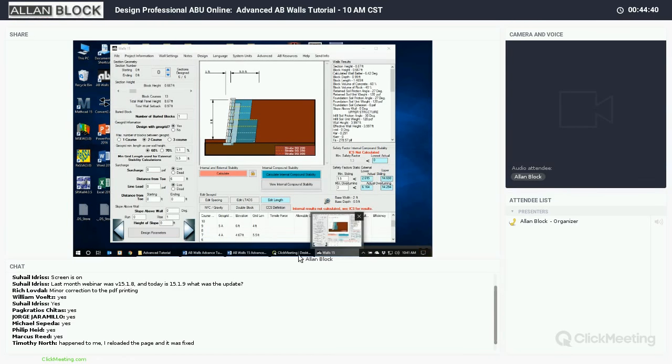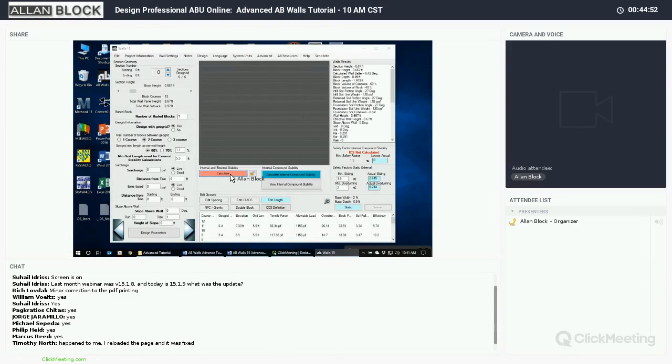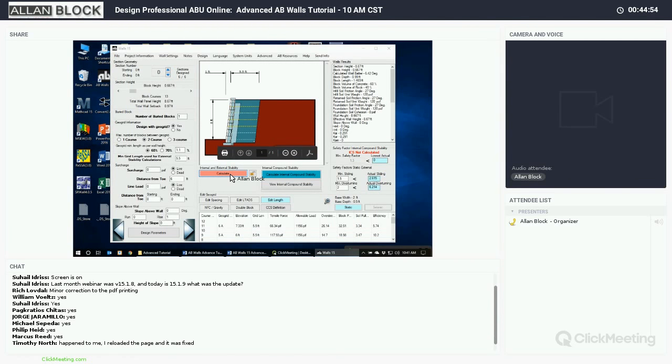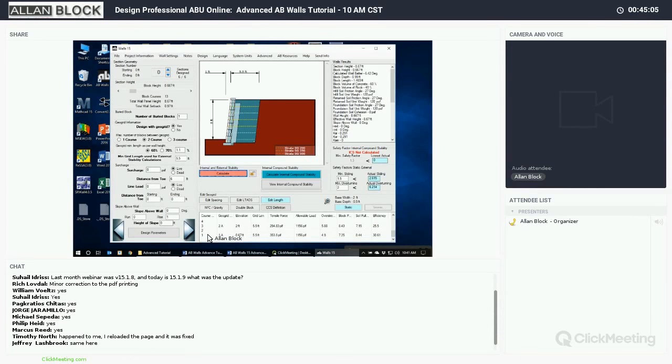So, okay. I showed you the grid top and bottom, the top part. I want to show you how you can change the bottom portion a little bit, because there's some little nuances here. So again, I'm going to unlock this and calculate it, go back to that 0 section. Now I'm going to try to shorten that bottom layer of grid. Again, grid length is here. I'm just going to scroll down, and let's say I go to number 1. I'll make that 4 feet.